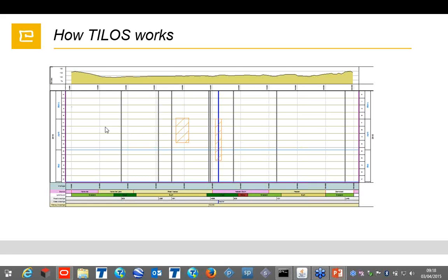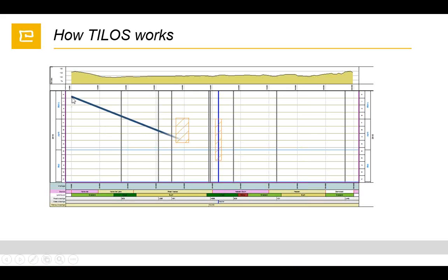When we draw our activities in Tilos, we can see exactly if there is any clash. This represents that at this time in the year and at this distance there will be a clash. Your teams will need to wait until the area is open, or work around and start working from the other side, coming back and completing the works. In this way you can make a faster decision, maybe starting your team's works 1 or 2 weeks later, and they will not have problems on the site.